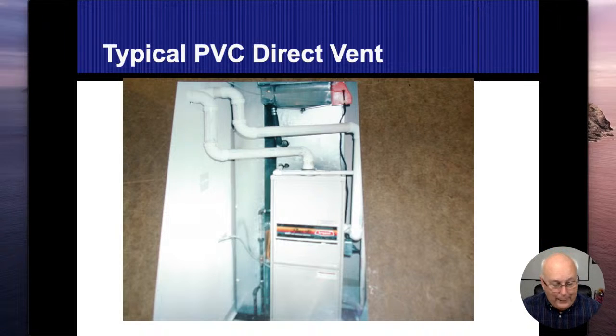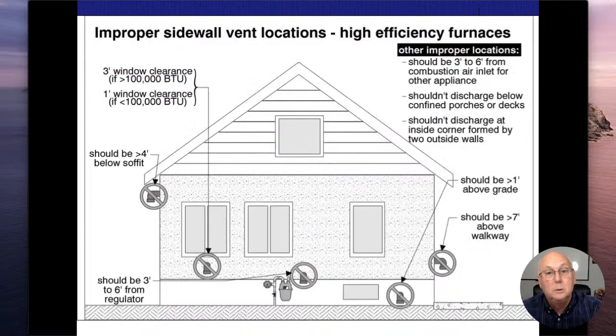I have nothing to back this up, but in my opinion, if you bring combustion air from inside on a high efficiency furnace, it's the same thing as being an 80% furnace. The amount of air that flows through there that you're using for the fire and blowing back outside is, you might as well just buy an 80%er and leave it at that. But that's just my 2 cents. I like to see both pipes being used when you can.